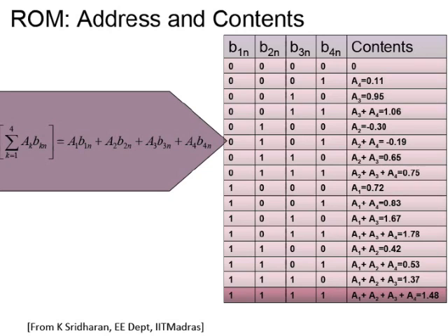So you have n cycles because there are n bits for an n bit number. For each bit significance position, you look at all the bits, you index, you get it, and so on. So what you have done is replaced multipliers with table lookup. Now, is it useful? Is there any benefit? You can ask that question. But the first point to note is that you can get the same answer by rethinking how you implement the algorithm in a completely different way. What was done through multiplier adder is now just lookup adder.